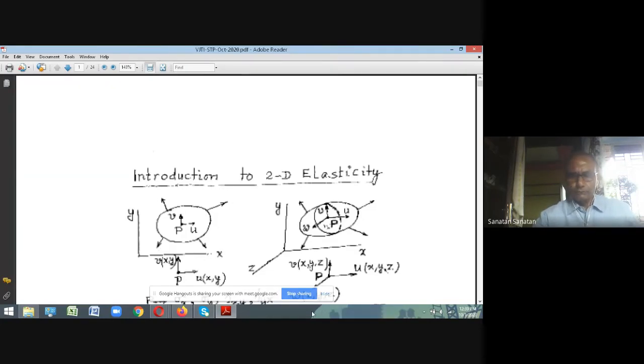will be gone. So if you want to find the displacement functions, you have two of them, and I'll show you within a couple of minutes that you can write the differential equations in terms of these two displacements, as in the case of that one-dimensional strength of materials problem. We wrote the equation in terms of displacement. The displacement of the common point was u, and that u is determinable because the displacement has linkage: the segment left and segment right have the same displacement u.